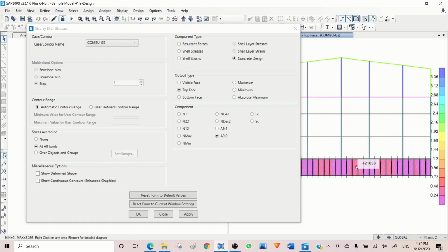So you see, vertical reinforcement is different because in some areas you have piles transferring load to the piles, causing this because you have a kind of span here, and this wall beam is spanning between piles and transferring load from columns to the piles. So this number here is more than here. You see the ratio change. So you need to see what ratio you have in each range. You may go for the maximum one, but you can't average here and here together because definitely you need more reinforcement here. So you need to see if the ratio is reasonable and you can accept it, then you can use it for all along the wall.